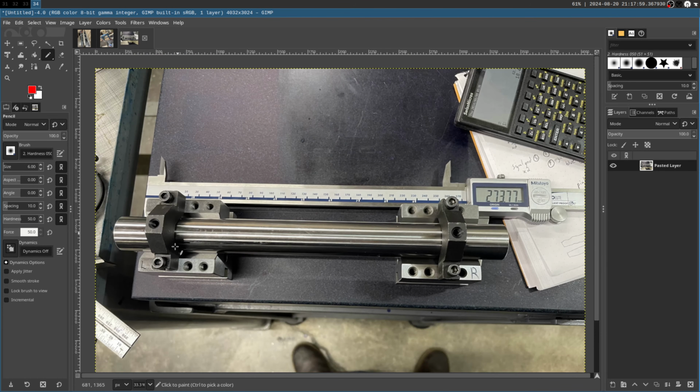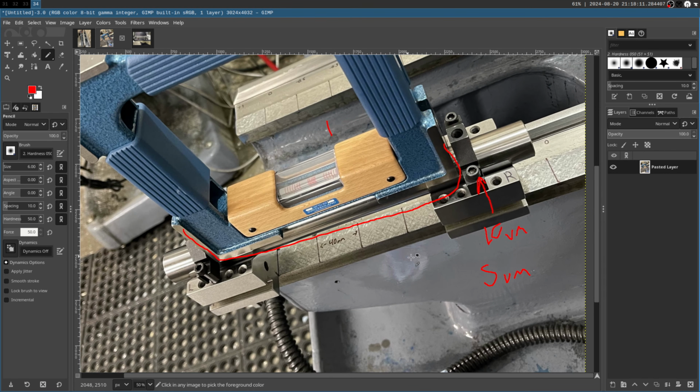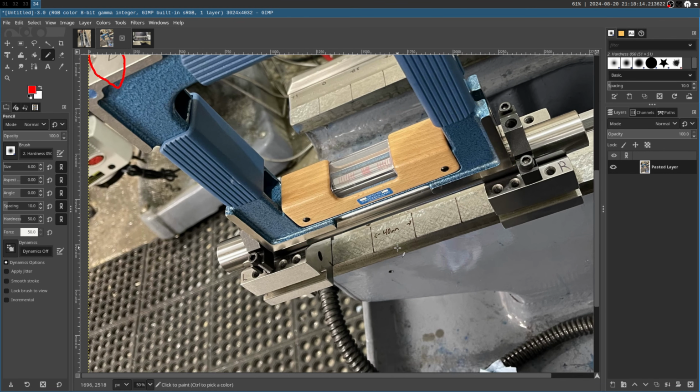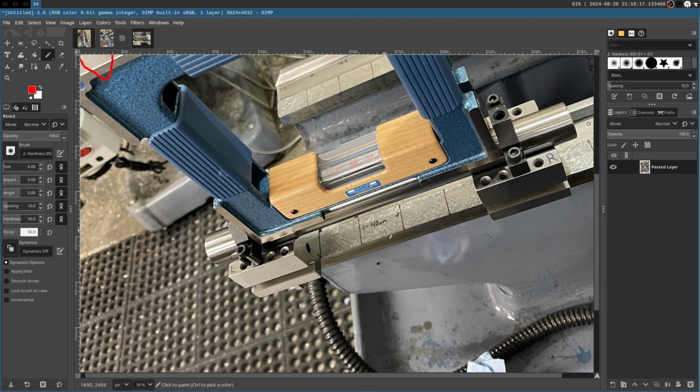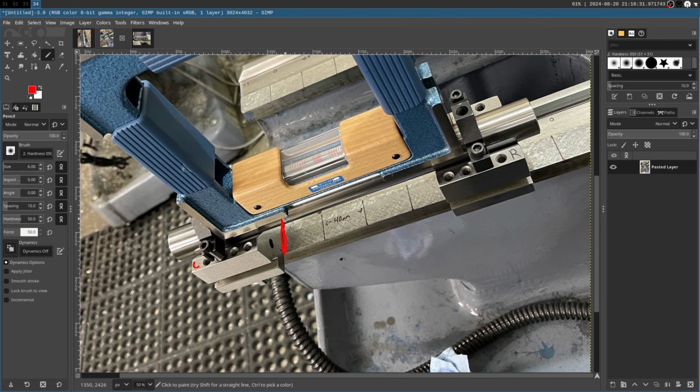Then what I do is I pick an edge that I want to be the reference surface on the dumbbell, and I'll slide it across, and usually I'll take a photo. This photo is actually one of those photos. It's basically a reminder to me of how I took these measurements. In this case, I see that there's 40 millimeters between these, and I see that the back side, the left side, is the surface that I'm lining up with the line. So I'll measure with that line, then advance the dumbbell and measure with that spot here, and advance the dumbbell again and measure at that spot there.